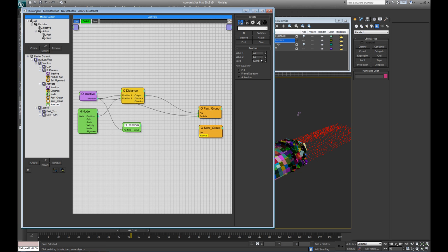So what this actually does is create a random number for every particle that passes through it. We have around 1700 fragments, so it will calculate an individual random number for every fragment. At the moment it goes between 0 and 1. I'm going to leave it at this, and for the new value per call, you can take it, or you can just put it on animation if you want. Then every fragment will have the same number all the way through the timeline,